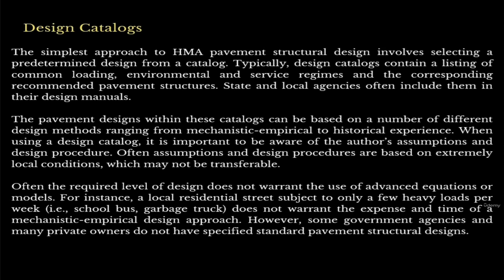Also, depending on the range of traffic, they'll give you parameters. What was the traffic? And it's an arterial road. You need to have these layers. If it's clay, you might need to have this, and then you use those catalogs for your design.